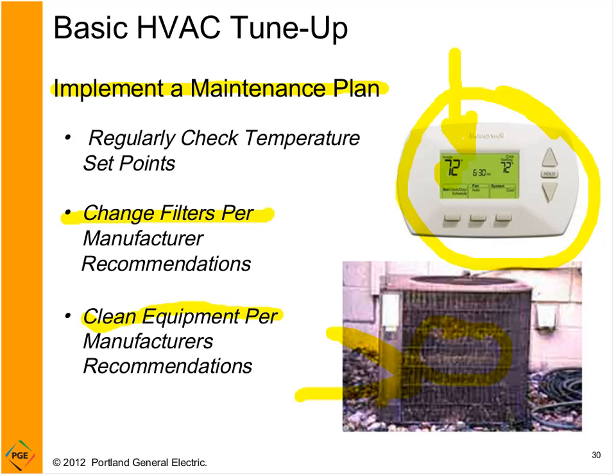And so I've had customers tell me that they come out here periodically, depending on where these are located, and they'll take a soft bristled brush and make sure there's no moss growing on the fins, and they'll pop the top off here. Of course, you got to make sure that you're again following manufacturer's recommendations, because there are some safety issues and there's some delicate equipment here that you got to be careful with how you're handling it. But you don't want leaves, for example, inside here fouling up again the potential heat rejection. You want to optimize the heat rejection here at this site.